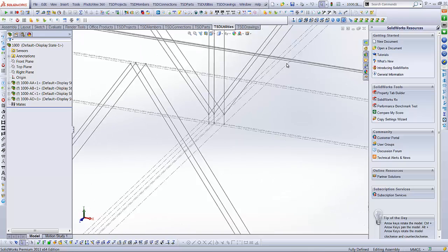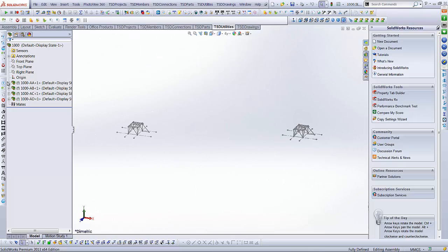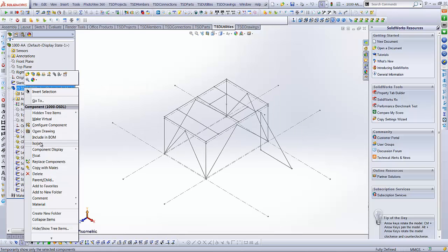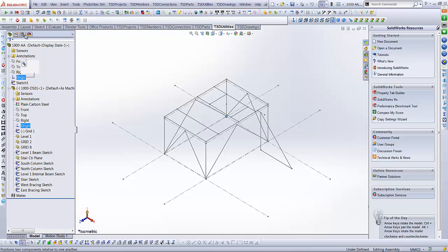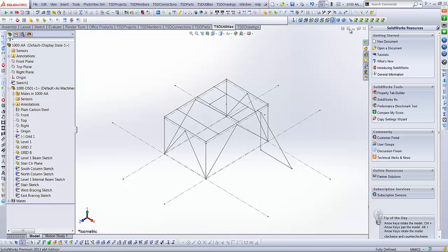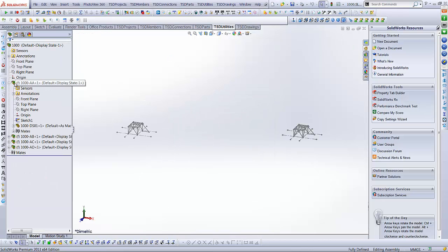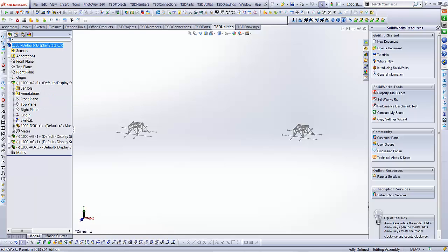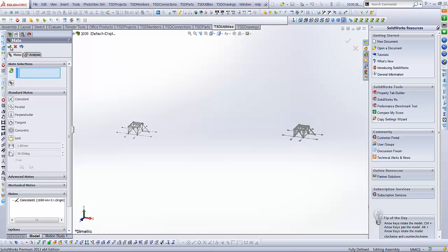Okay, now you'll notice that there's a little bit of an offset issue going on here in one of them. Obviously this one I think is in the wrong place because we didn't check that one. So I'll put those on top. Yeah, I lost the paper clip, so I'll just bring it back again. Yeah, that's okay. It must be the assemblies in the top level. Okay, all these aren't lined up. Yeah, it's funny how that functionality is now gone, where you used to be able to just drag and drop and it would line it straight back up on the origin.